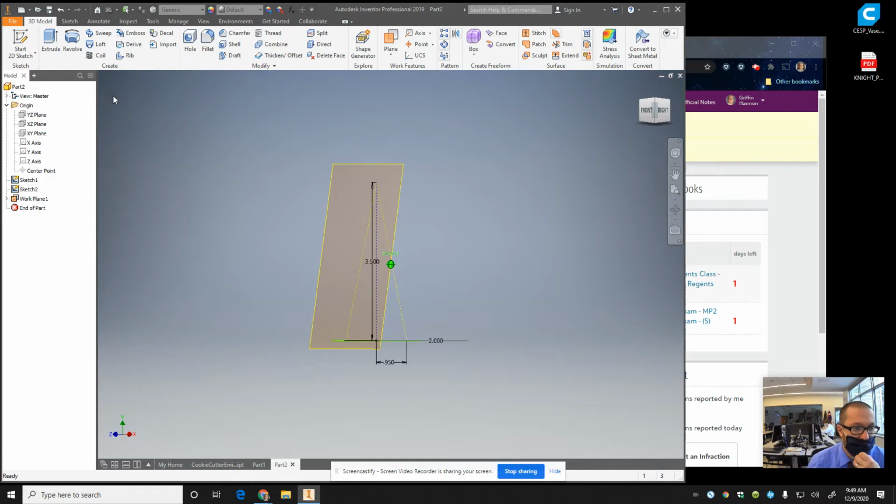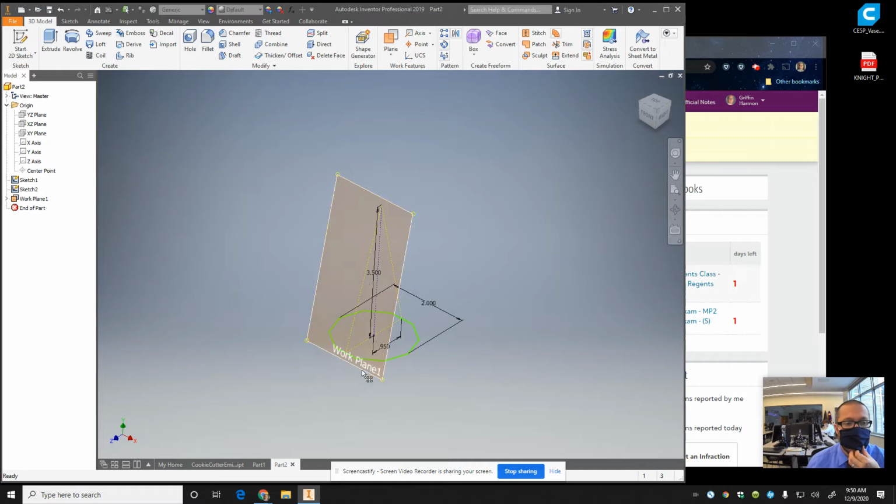All right. So now what? Well, the whole reason I made the octagon was simply to make this work plane. I'm not going to use that octagon or decagon for extrusion, just to make that single work plane. Could have done it with a square, I guess, but I might end up making other work planes on here to make different leaves. So let's see what happens. Start a sketch on this work plane.